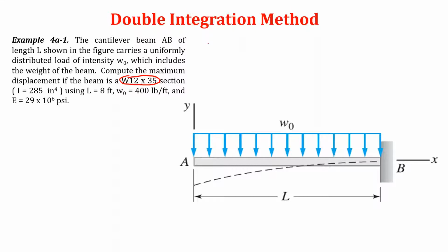This is an I-beam. What is the name of its shape? It has an I shape. Now for steel beams or columns, you notice the I shape, but it is called W because it means the flange is wide. This is the flange.